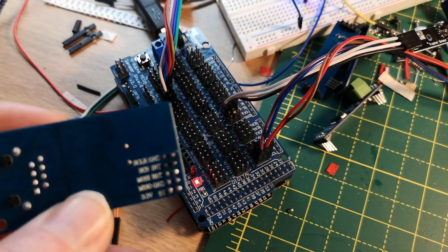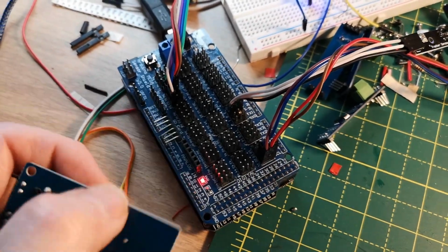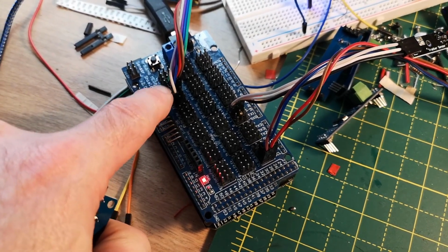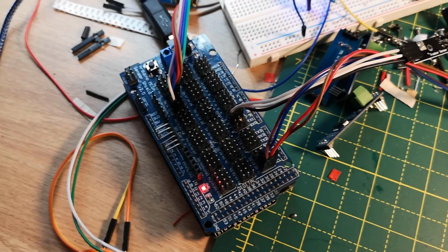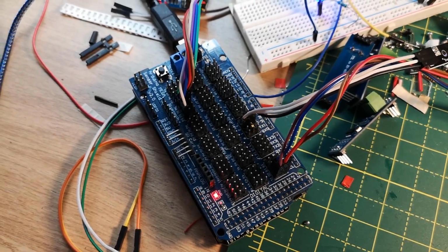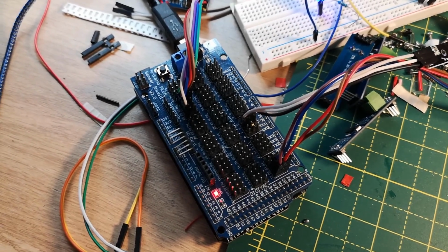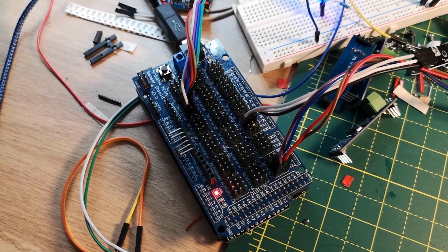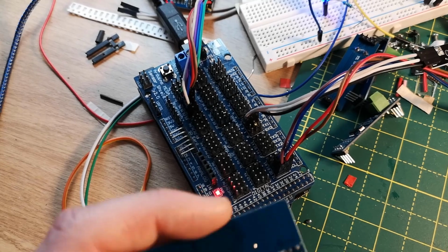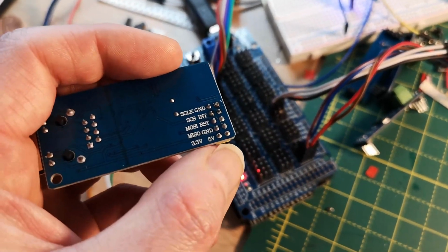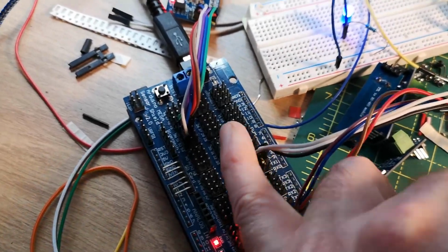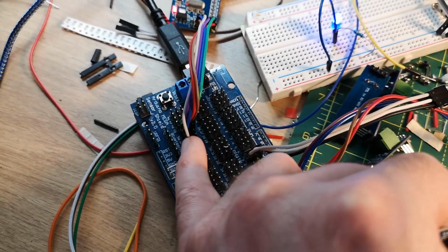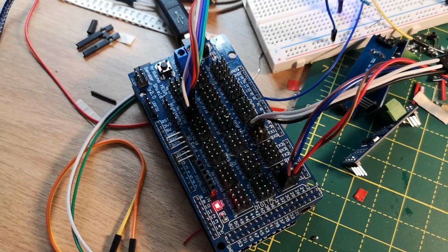So there is an override, so I've plugged SCS into 53 just to conveniently take up this entire clump, and it just takes a little bit of config, one extra line in the sketch to tell the Arduino to look to pin 53 for that connection. Also, of course, there is ground and 5V, which are just plugged into one each of the ground and 5V headers on that little block.